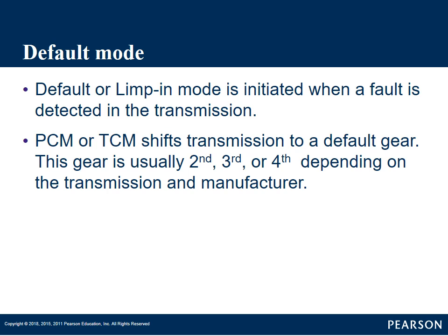Many of your early 4-speeds, it was second gear. As we've added more speeds, we change what gear ratio they've locked it in. Okay, so if you get a transmission, the customer says, this transmission, my vehicle, it starts out really doggy and it never shifts into high gear. Check engine light's on. Or maybe sometimes check engine light might not be on.